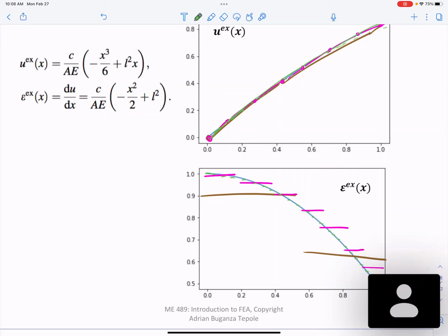So what you should do is refine the mesh and then see how the solution changes. You want your solution to not change too much at a particular location of interest. Let's say you have your part and you are interested in the stress at a particular region because you think it's going to fail at that location.